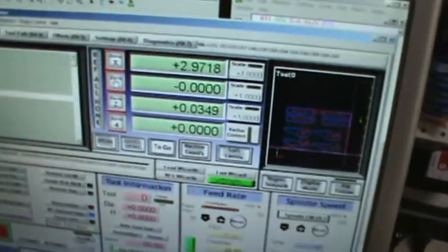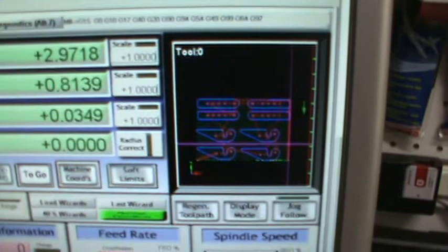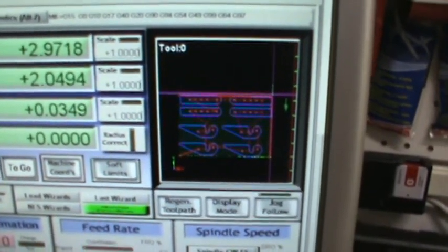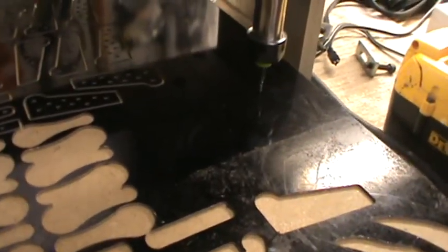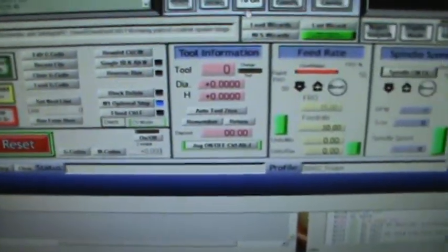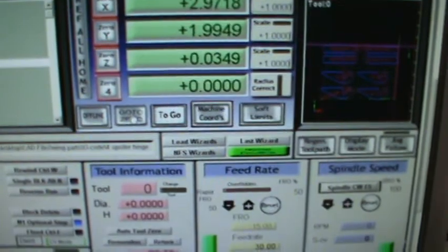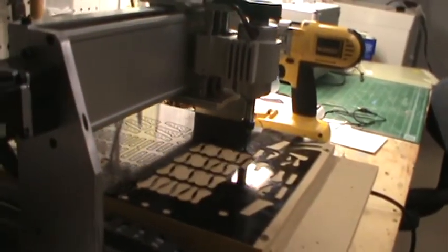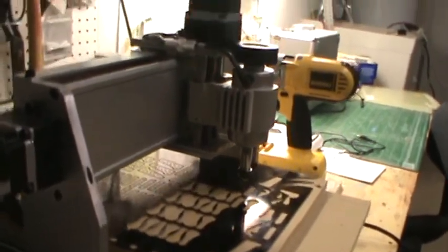Then I'm going to do the exact same thing for the Y-axis. I'm going to bring the machine up until it hits the bright pink line, then bring it right back. Same thing back over here, make sure there's enough material, which there is, and we're done. Then the go to 0 button, quick go to 0, and we'll watch the machine come across by itself to the point we selected, and our bit should be right on the material, and it's pretty dang close.